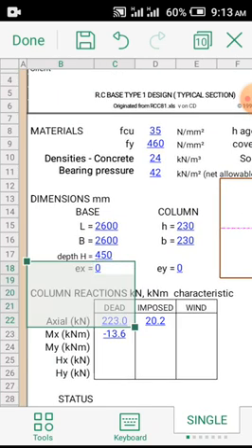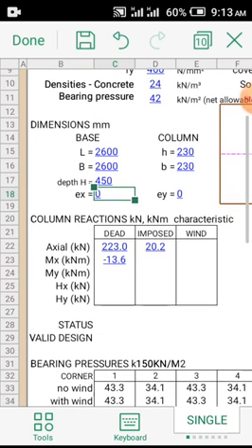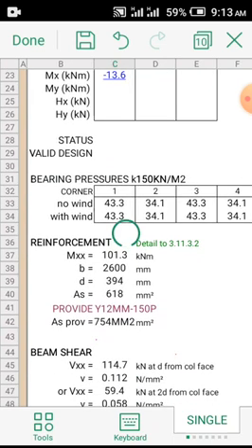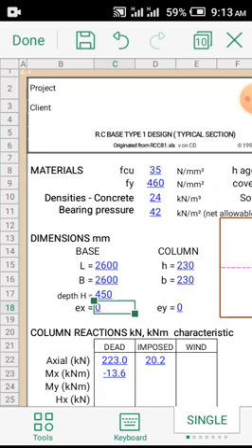So it's advisable when you have a bad soil like this, maybe you use a raft foundation instead of a pad. We can go and in the long run get what will serve, but it's better you use a raft, because that soil is actually mushy, it's very bad.